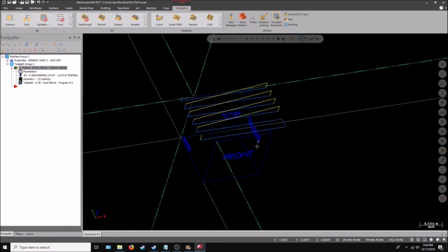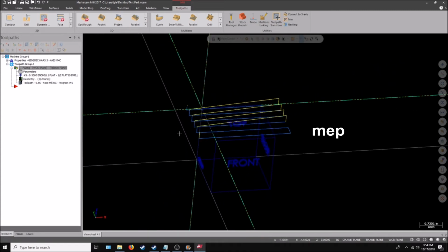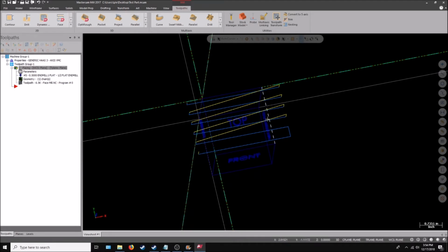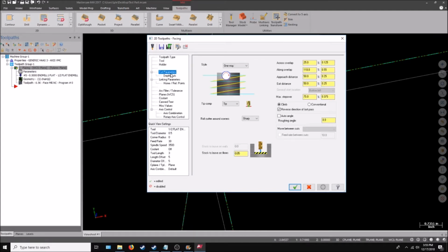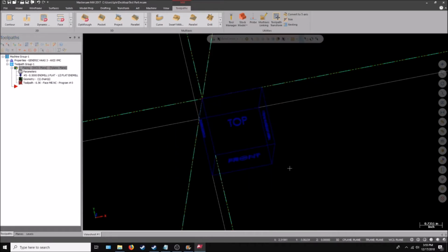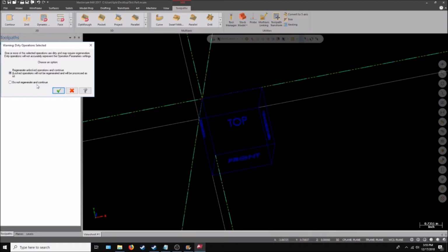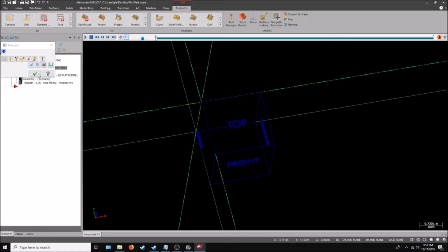And look, it generates a toolpath. It's going to come down in here and go bam, bam, bam, bam. And it looks like it's set up for one direction. So it's going to come up every time, go back down, come up, back down. But if you messed it up, like you almost certainly will, you click on parameters and go to cut parameters, and we can choose our overlap. We can do our style of stuff. Let's try a zigzag, and then we'll click on that again, regenerate, and it's different now, and we can even visualize it like so.